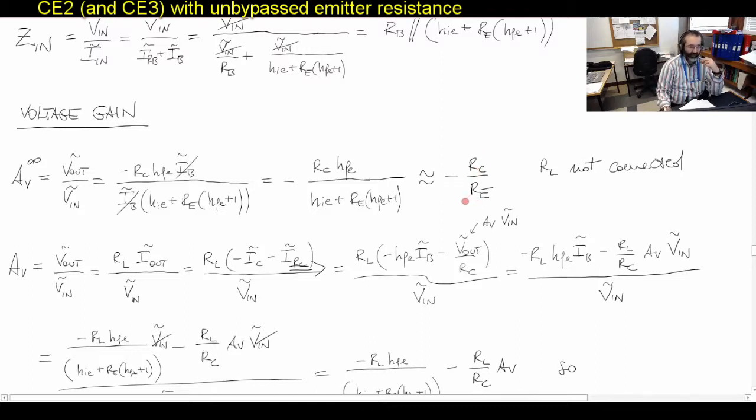And this is effectively the key point I wanted to make by showing you this specific application where CE has been omitted completely. By removing CE, now I have an opportunity to define the voltage amplification of the circuit completely and only by resistors, external parameters.